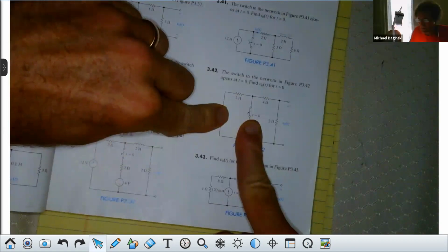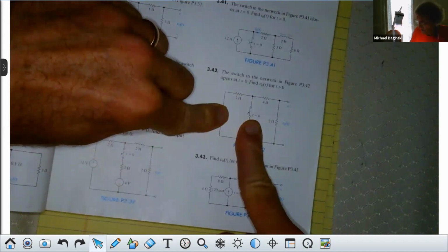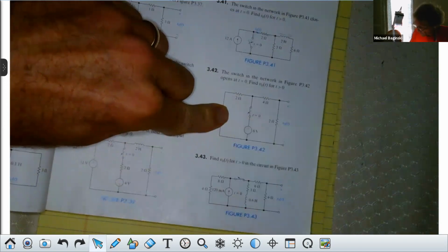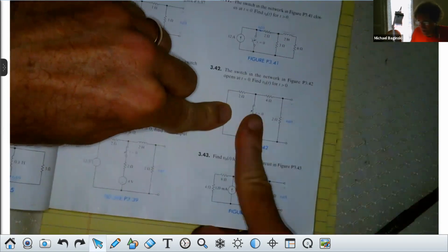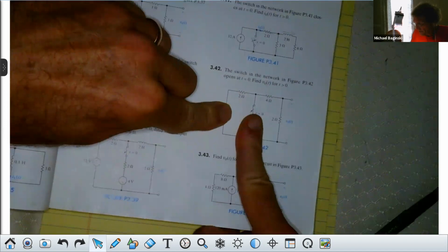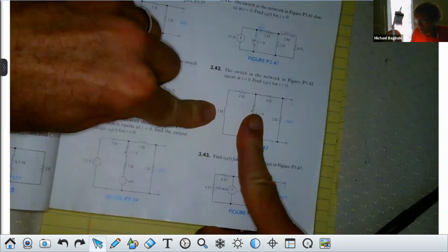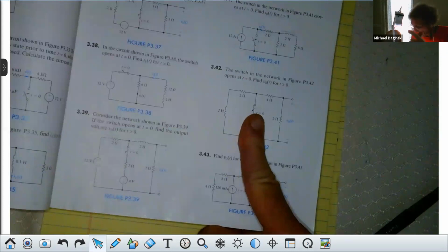Thumbs up if you do. Can you all see this or not? I'm looking at people. I'm not sure if you can see what I'm doing here. Y'all see that? There's 8 ohms, right? It's here. 2 plus 4 is 6, plus 2 is 8. They're all in series. There's no parallel. Y'all see that? The inductor is right there. Are you with me, class? This is critical. So right off the bat, I got R Thevenin. I've got the current as t goes to infinity, right?